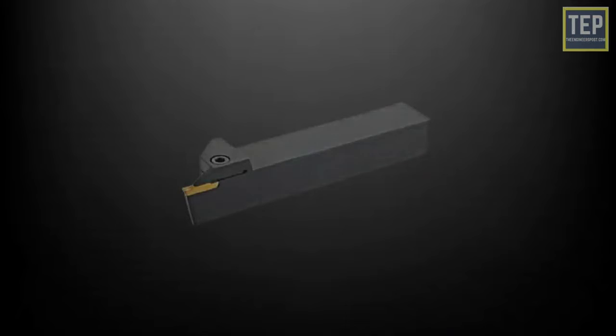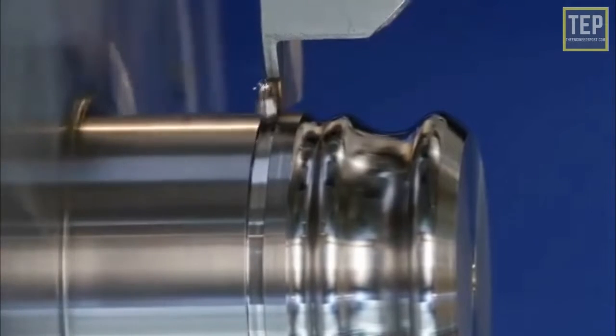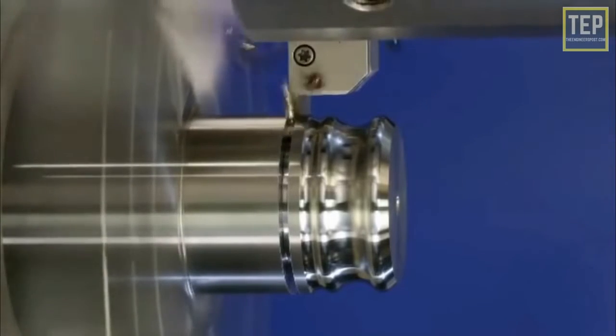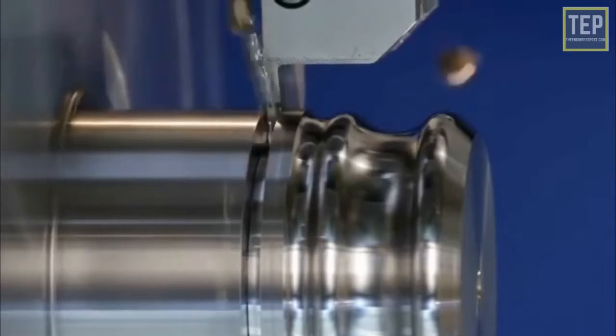Grooving tool. A grooving tool is similar to a parting off tool. The cutting edges are made square, rounded, or V-shaped according to the shape of the groove to be cut.